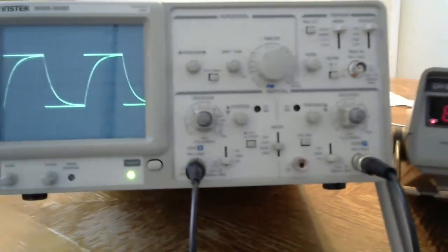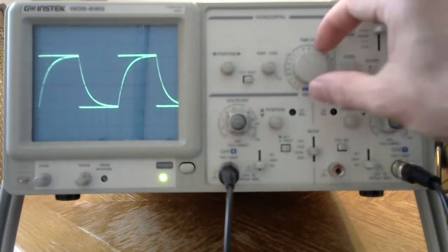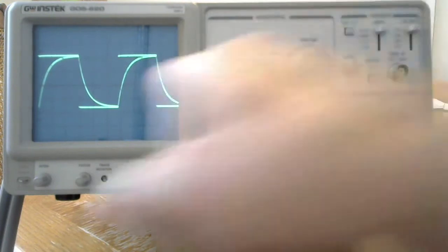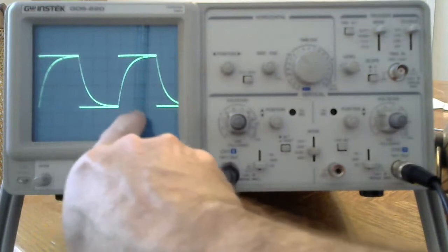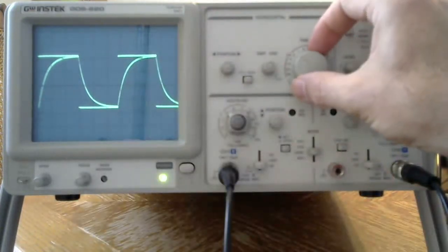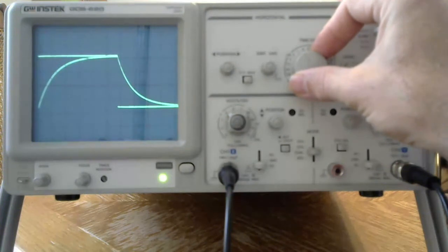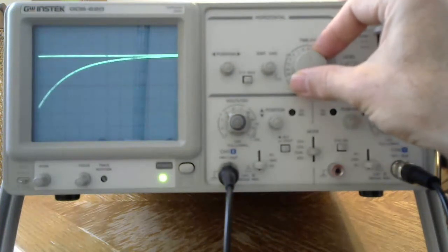Now, if I don't change the signal, I can actually zoom in or out of the picture, right? So if I change the time base, this time base tells me how many milliseconds every horizontal box represents on this screen. Okay, so if I increase the time base, so I have more seconds per box, then looking at the same signal, the signal is magnified. I'm not changing the signal, I'm just zooming in on the signal, right?